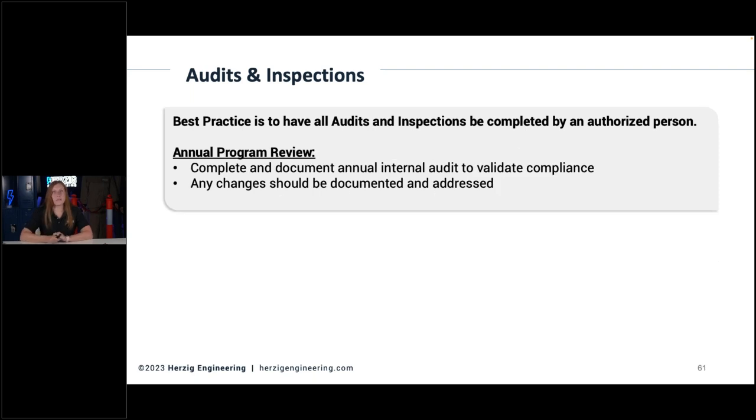There's also the program itself, the written policy documents and things like that, which need to have an audit, internal at least, to validate that it is still compliant. Again, the 70E updates every 3 years. Sometimes there could be changes that require you to add a little verbiage or change how you approach electrical lockout tagout. For example, the 2024 version added some words as far as the verification of absence of voltage. Really, it was just to clarify what they meant, but it is still important.